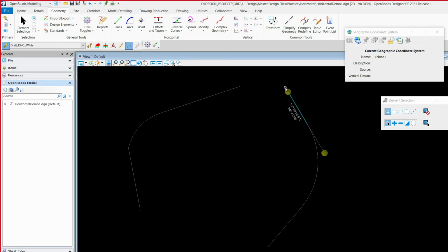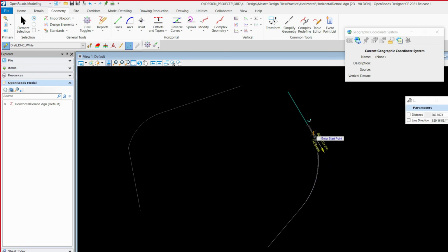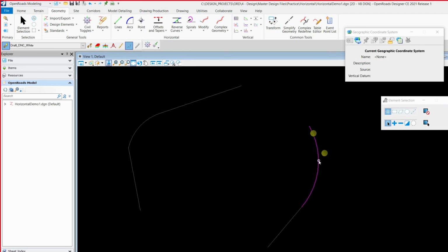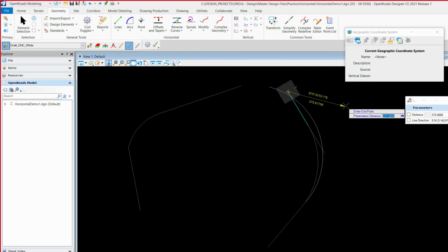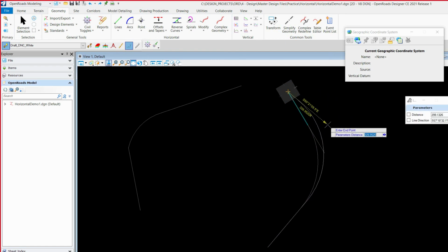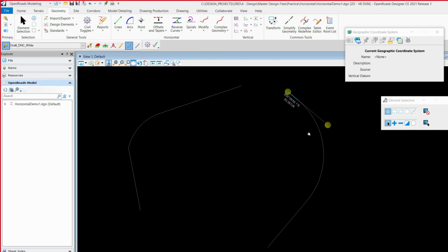You also can get issues if, say for example, the line is too small. It'll still remember that the line is there, and it'll connect to the tangent. So if you get to a point where it's too big sometimes, then it'll red dash itself out if there's a geometric impossibility that you're trying to build here.